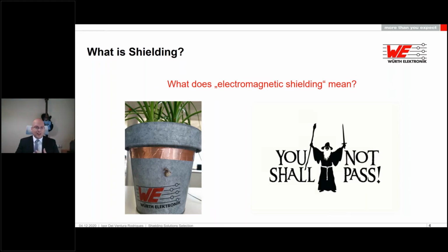your own device. So shielding can be really, really important, because sometimes we will face situations where we are in the EMC lab, and perhaps we cannot modify our PCB in terms of inserting more components, or simply there will be no electronic components that will sort out that specific noise issue, and then we will be utilizing shielding.